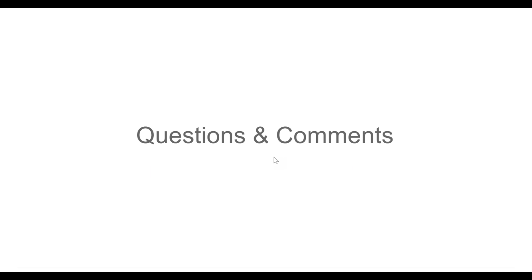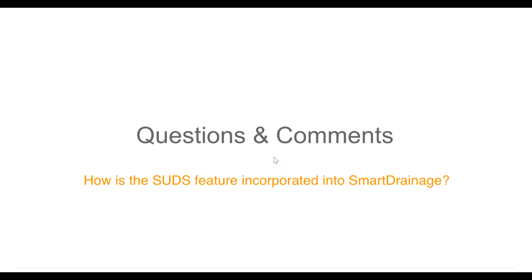Glenn asks, how is the SUDS feature incorporated in SmartDrainage? Actually, one of the main reasons we created SmartDrainage, and are looking at expanding it, is to look at bifurcation, SUDS, and things like that. At the moment, it will bring in all the information to do with storage or infiltration structures, as well as flow controls and all associated attenuation or flow control structures you have set up within Flow.